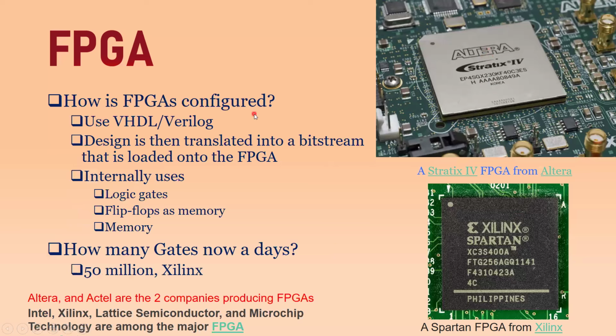So how is an FPGA configured? That is the basic question. When you want to implement any logic inside it, how do you program it? You would have the usual procedure of what you do while doing ASIC design. You start with the schematic entry if the logic function to be realized is of a small level. But if the logic function is more than 100 gates, let's say thousands and thousands of gates, you basically take help of a hardware description language. So you're writing code to describe the hardware, what you usually do with an ASIC. You will do the same for the FPGA configuration as well.